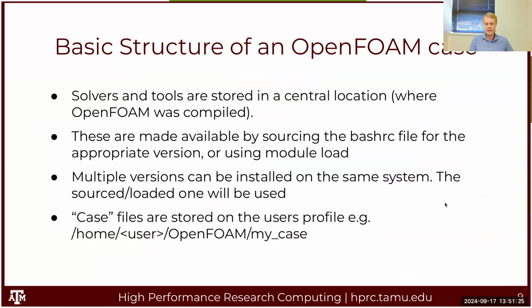This is just a summary of what I said. One thing I want to add is that when you install OpenFOAM, it just puts all of this stuff in a folder. And you can tell OpenFOAM which folder it should look in for all the components and tools, which means you can have as many versions as you want installed at the same time. You just need to make sure that when you open a terminal, you point to the version that you want.